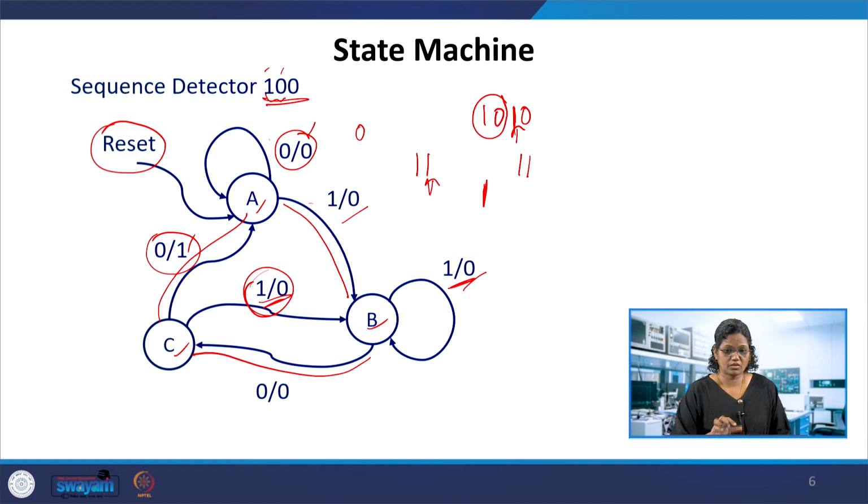So we change the state memory code in the always block to include reset, so that at any point of time you will not be stuck. If the state machine is not moving from one state to another, you can use the reset to bring it to the initial state. We will be doing that Verilog code as well, and we will include this reset in this case.